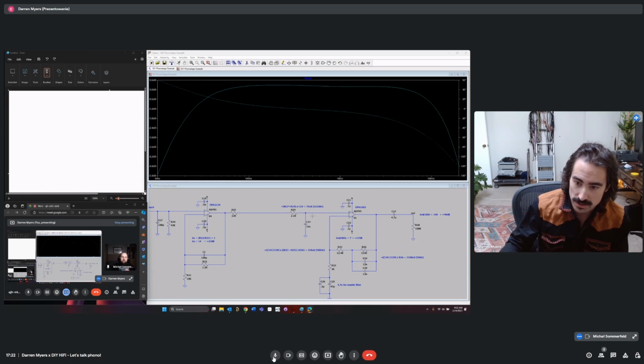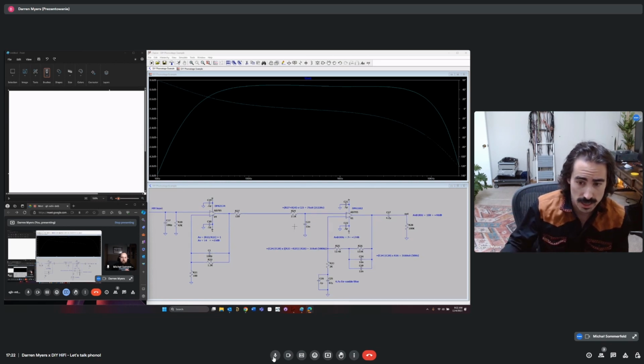So we need to be careful that we don't create some sort of crazy parasitic capacitance. Probably from 2.1K it wouldn't matter too much, but it's still a design philosophy that I always follow, to optimize that layout, where we would want this to be small and really short, and this is the trace that we would actually route out to connect the two stages.